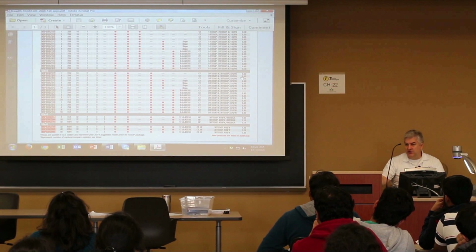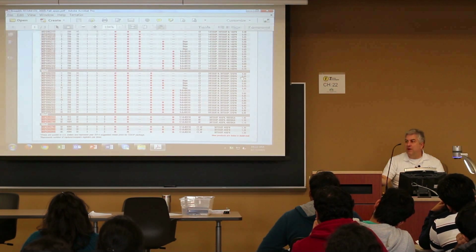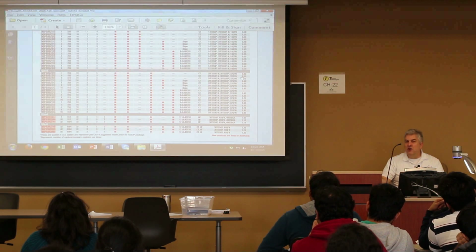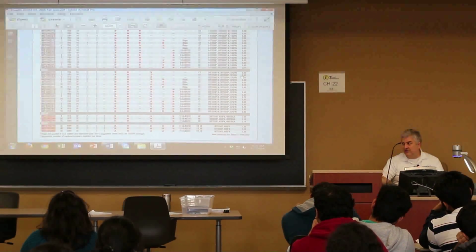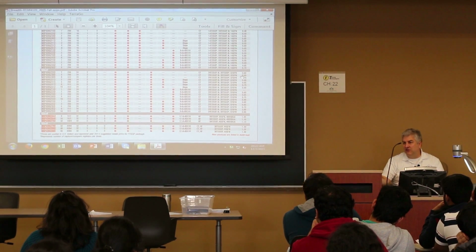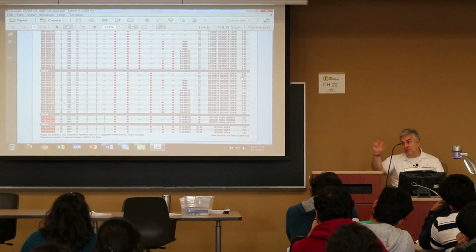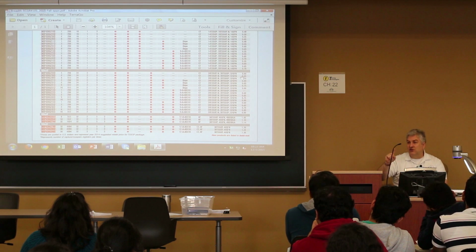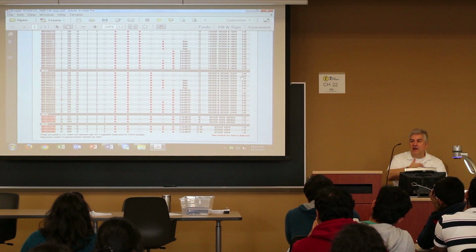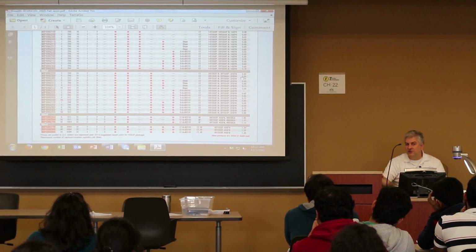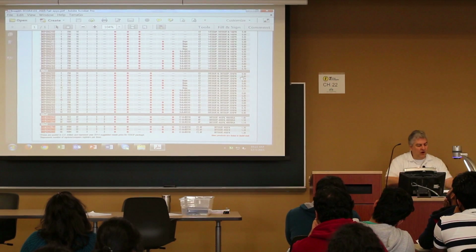I worked on a phone project where we woefully underestimated the amount of computing power we needed for the phone. In the end, we had to overclock the processor and chew up lots of battery power doing that because we had a lot of computationally intensive operations. At least we had a processor that allowed us to double clock it when you needed the processing power and then back off when you didn't. We paid a little bit more for that processor, but in the end we used its capabilities and it was worth it. So that's one aspect of, all right, what do we choose?